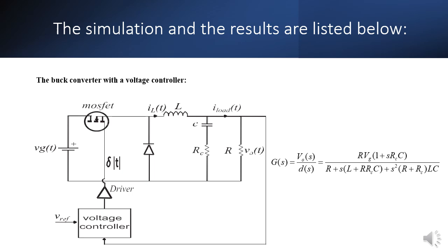Typically, the buck converter's design goal is to reduce output voltage ripples. The current in the RL circuit exhibits exponential increase and decrease. Either the input voltage is equal to the voltage across the diode or it is zero. The magnitude of the ripple in the output voltage is determined by the converter's output filter, which smooths and attenuates the voltage waveform. In order to achieve the appropriate level of voltage stability, the filter design is crucial.